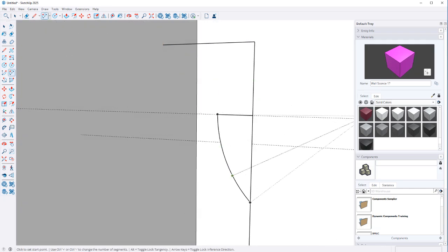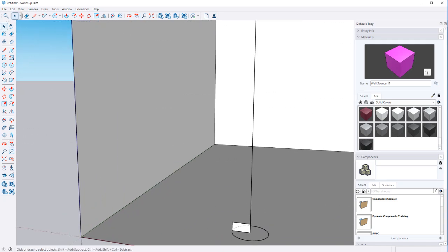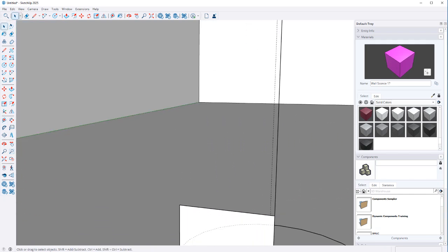We'll do this, so we'll get this part of the bowl. You know what I didn't do is we didn't offset this yet. So that pole's probably half an inch thick, so we'll make this offset. No, we'll make the offset a quarter or half inch so that we have a 1 inch thick pole on this. 0.5.